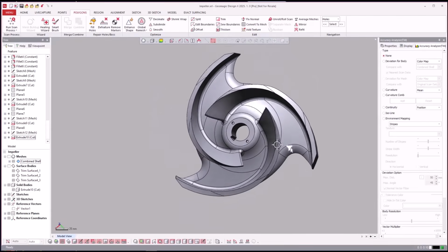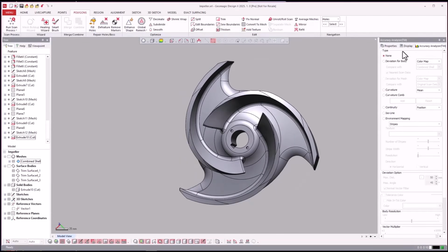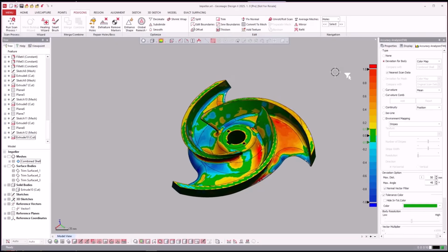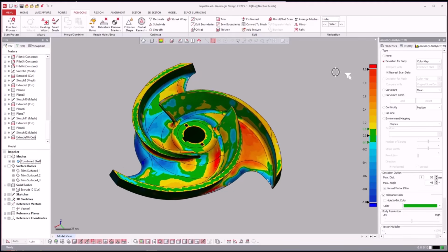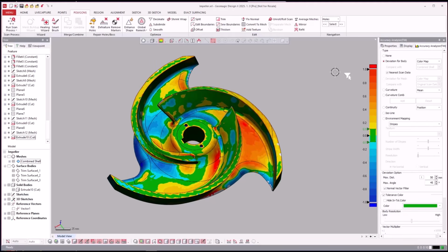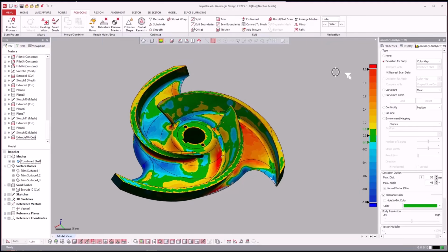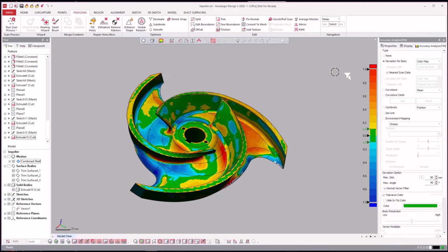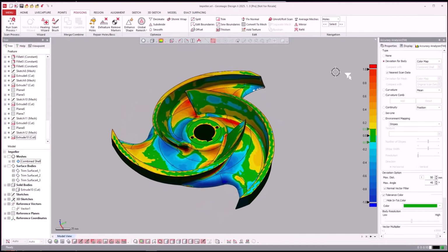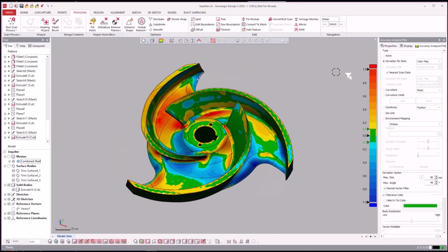There we go. And then turn on the accuracy analyzer, and you see this happens with these types of parts, these castings and that are machined and stuff. There's lots of deviation. There's deviation for reasons that it could be a used one, like we talked about before. It could be the part made on the Friday before Christmas. It could be that this was a failed one, that failed inspection, was thrown in a corner. Who knows? And now we're scanning it because we don't have anything else to scan. There's lots of different reasons why there's a lot of variation in these parts.